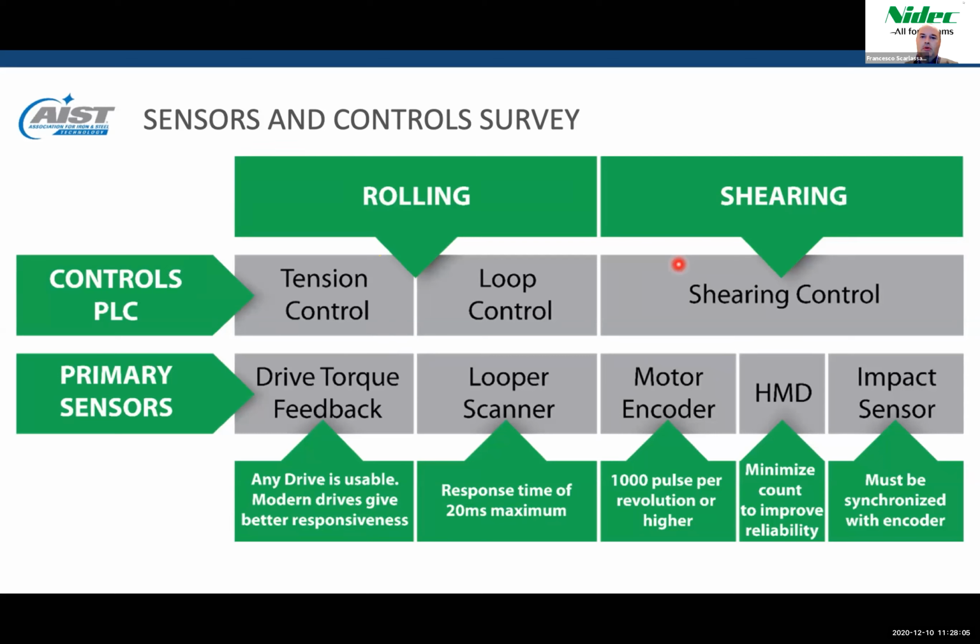Keeping all the control in the PLC also allows for better control through feed-forward control and also tighter integration with the entire control system. Just think, all the systems, shear control and mill control cascade, are running in the same PLC. The control communication bus is, of course, equally important. Here we must have a deterministic bus with high speed. And any modern PLC using Profinet, Profibus, or Ethernet IP is capable of doing the job.